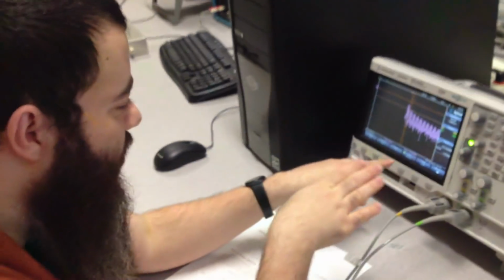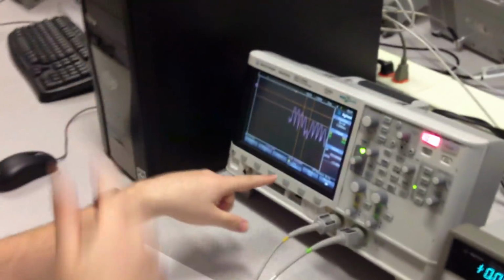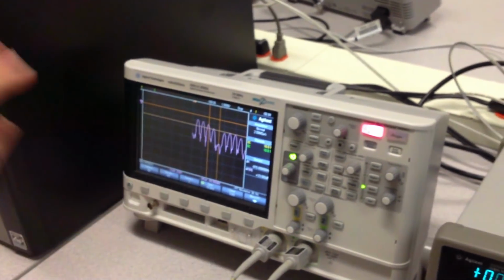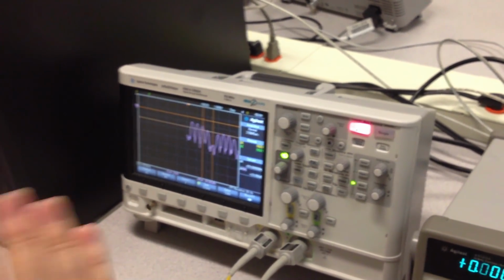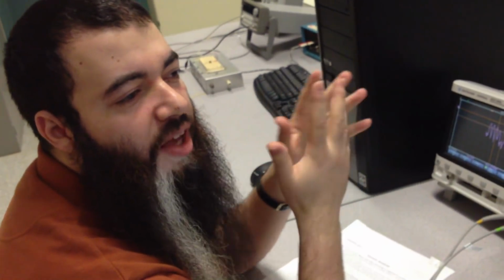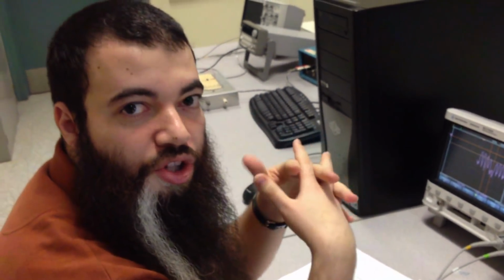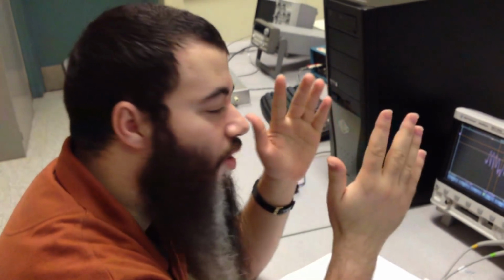Okay. We want to make sure that this spectrum is correct. The numbers in this spectrum should actually correspond to the theory. How do we do this? Okay, let's set the span to 10 kilohertz again. We want to take values to make sure that these numbers correspond to the correct spectrum. We don't expect them to correspond 100%. This is a real system with real noise, with real problems. So we expect about 90%. I want the numbers to be close to each other, not 100% equal.